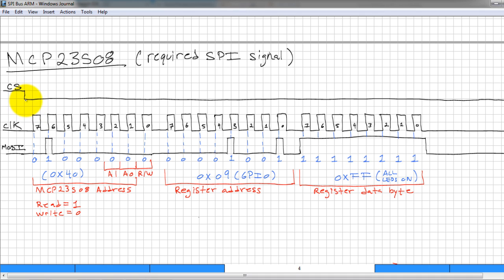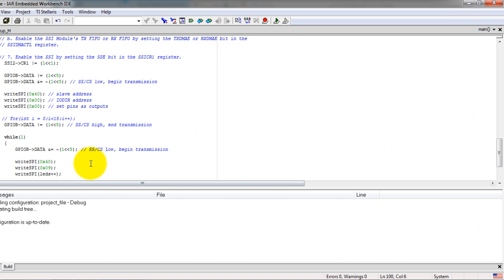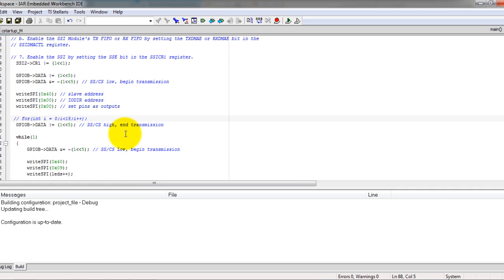There's a minimum required time in the datasheet that you have to wait after you have toggled this pin before you can start your clock. There's also another requirement where you switch your CS pin back to high after you're done sending data. And the only way to really find out what's wrong is to look at the signals with an oscilloscope. That is actually what I have done.